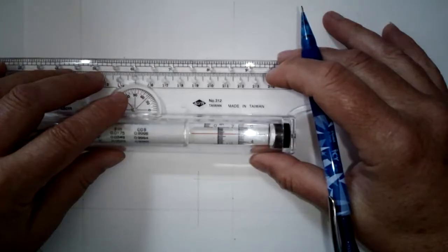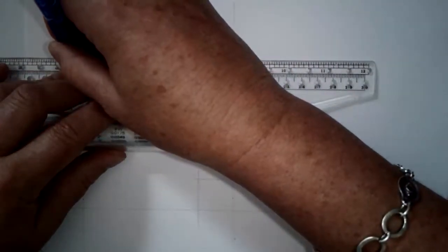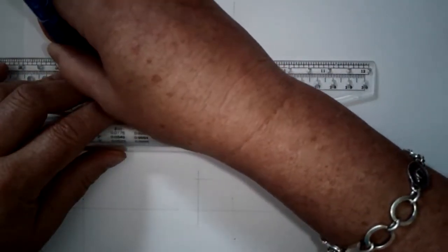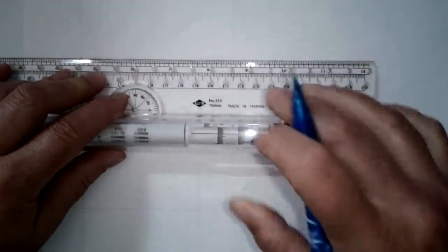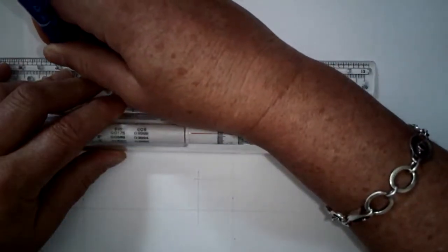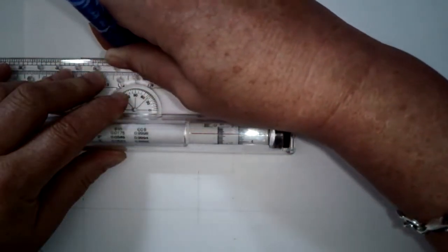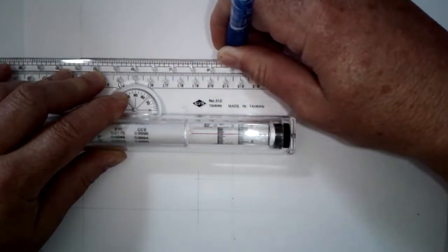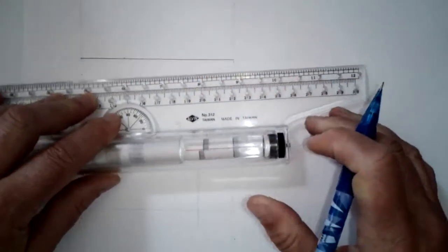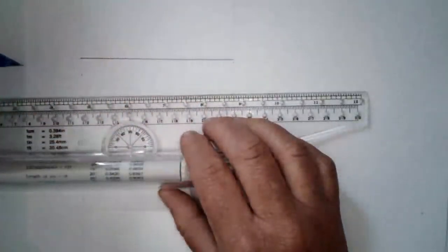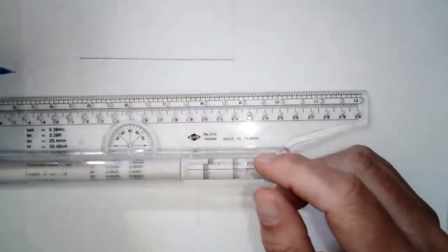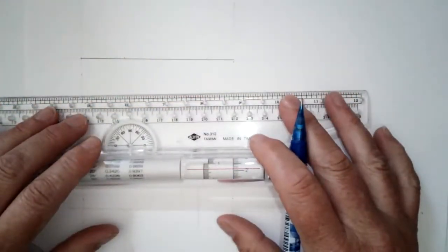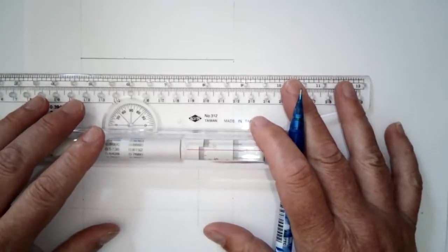So position your straight edge where it ought to be. Position your lead holder right over the intersections of the 2 construction lines. And notice that I'm pulling towards my right hand. That's the way that I draw. I go from left to right. If you are left-handed, you would go in the opposite direction, like this. Avoid pushing the pencil. Pull the pencil instead. It's going to result in a lot less breakage.